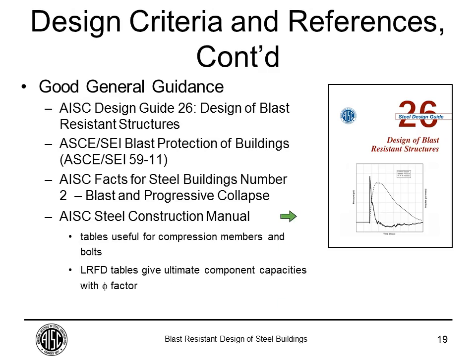Right here on the right, we have the Design Guide 26, which is a very nice, very well-developed document that provides examples on closed-form solutions, on how to use single degree of freedom analysis of components. It also has analysis of frame systems and discusses the application and development of blast loads. So this is another one that is a good start for you if you're looking into learning more about blast-resistant design before you get into the more comprehensive ones that we covered before.